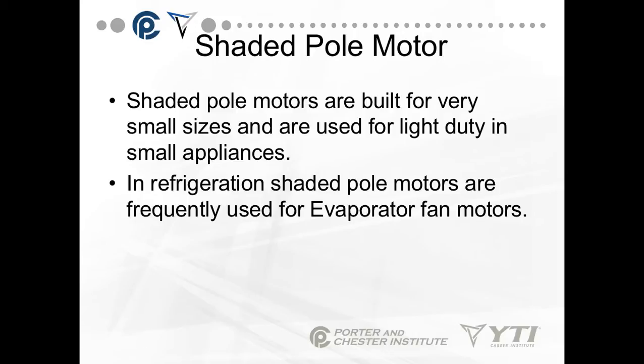Okay, the shaded pole motors are built for very small sizes and are used for light duty and small appliances. In refrigeration, shaded pole motors are frequently used as evaporator fan motors and condenser fan motors. So that's it. Shaded pole motors, 2 wires, very easy to work with.